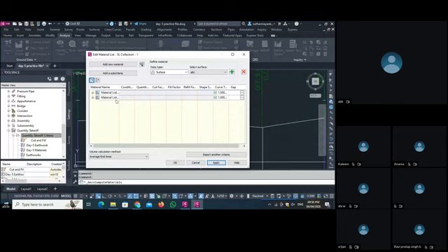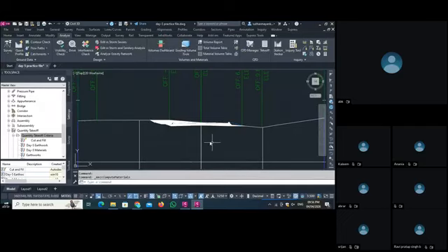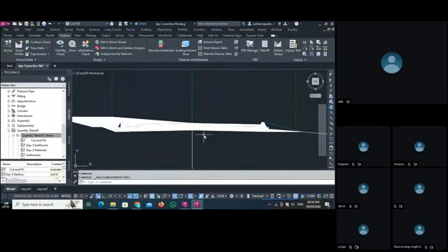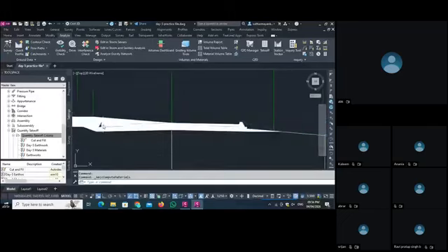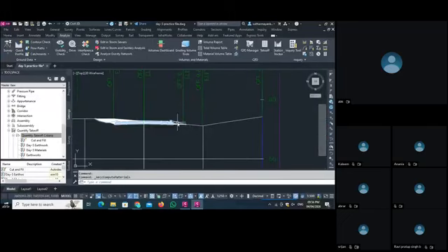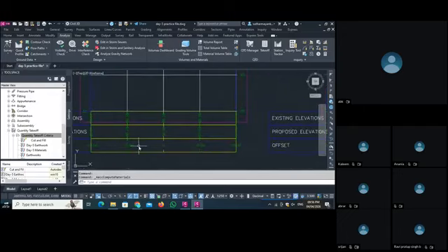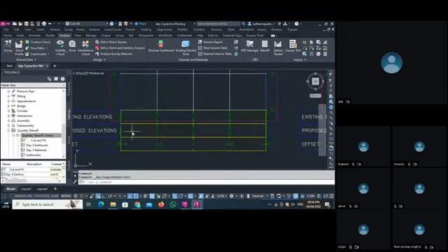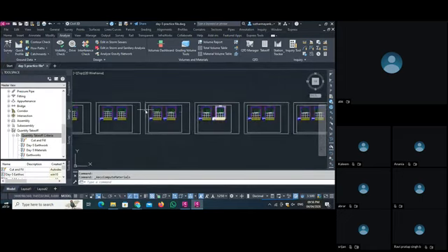See, these two things are set now. You click apply and OK. It will take some time. Now all the things are done here. Now you see your cross section here. The cut fill is here. The material we put already, the material fill is here. Cut and fill here. The ground profile is here. Corridor profile is here. So all the things are here. You can see all your offsets and all those things now work properly.